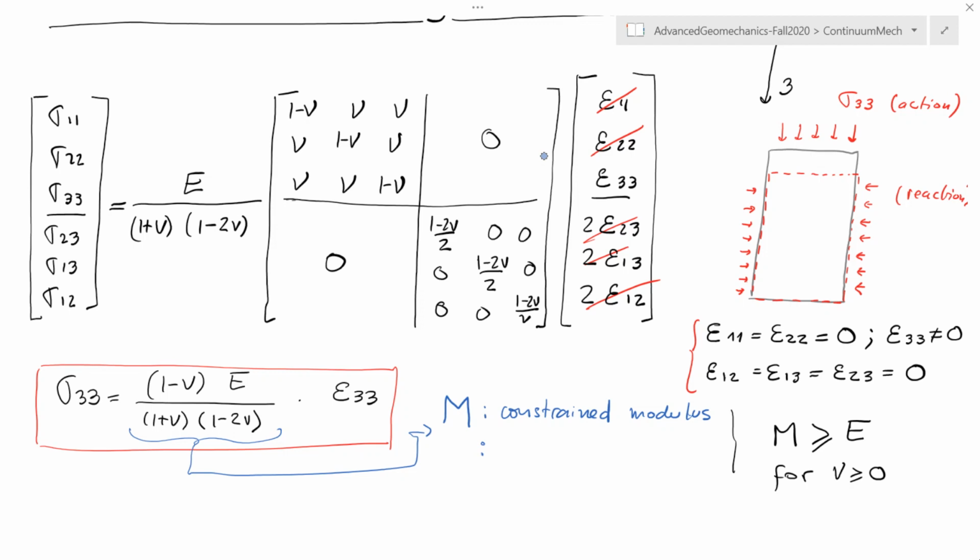So this is a very important modulus. And this is also called, as well, has a name of the oedometric modulus. This is the name which is given in solid mechanics. I have to say too that solid mechanics has been very successful lately in order to describe the evolution of young unconsolidated sediments over geological time. So it's becoming more and more popular in structural geology.